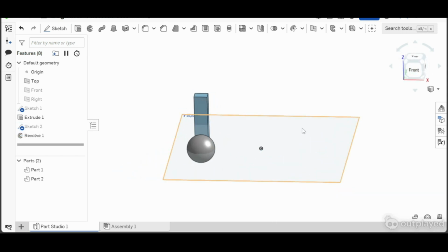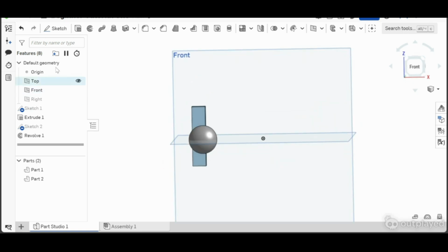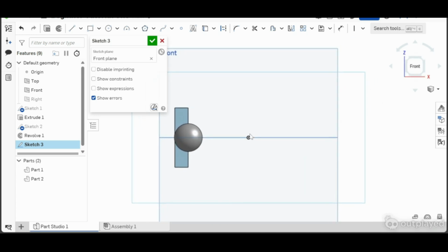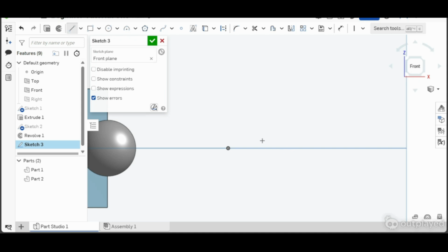So Revolve is really useful for symmetrical parts like pulleys or vases, and I will show you that right now. So if we get this front right here, and I click View Normal Sketch Plane, and I'm going to zoom in on this part, and let me create a 2D version of a vase. Let's say it's going to look like this. I'm going to quickly make sure that these are parallel, so this doesn't affect anything. And I'm going to make sure these are vertical.